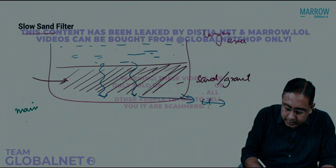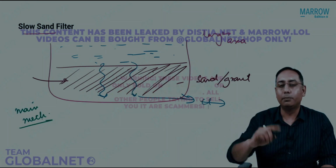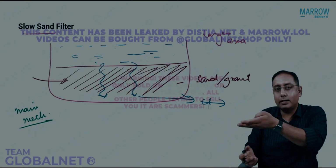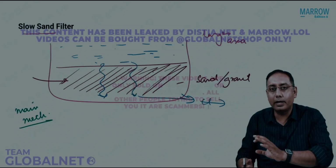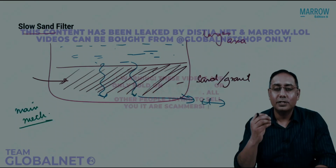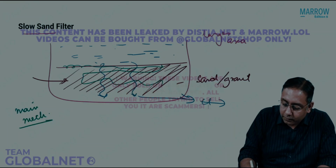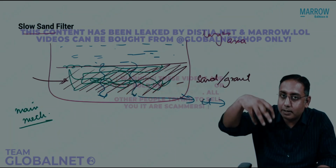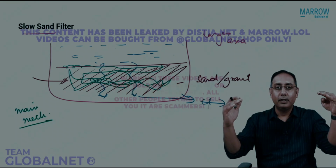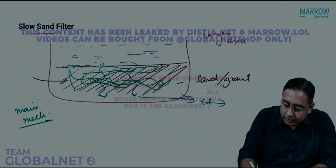The main mechanism in a slow sand filter is not the filtration. So what is the main mechanism? Beta, in case I let the water stand over here on the floor somewhere for a long time, don't you think there'll be algae or plankton over there? That algae or plankton will form here also. They will form inside the bed also, embedded into the bed. So there is this formation of the plankton layer.